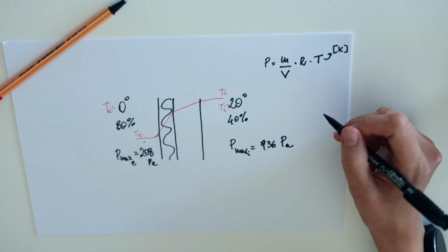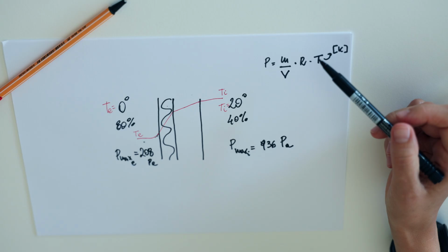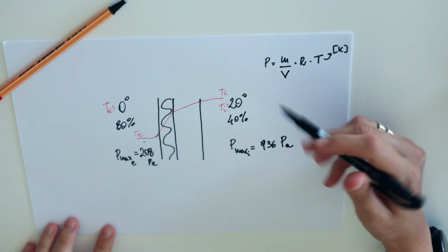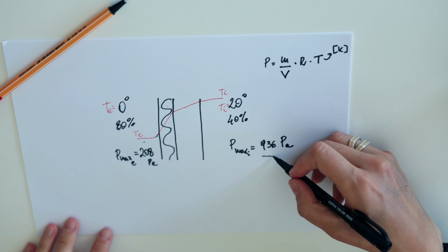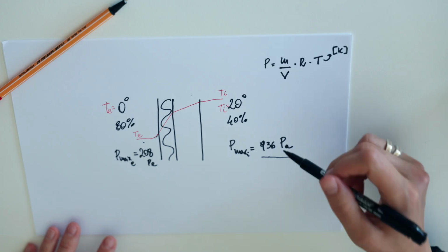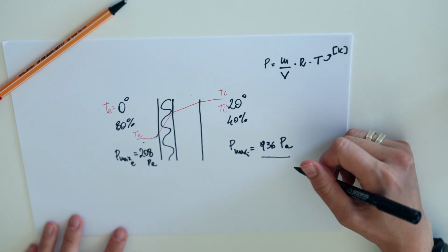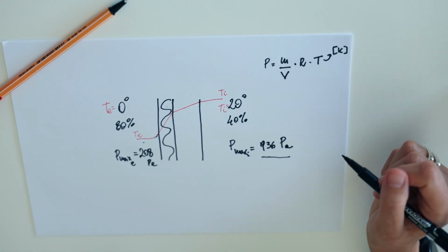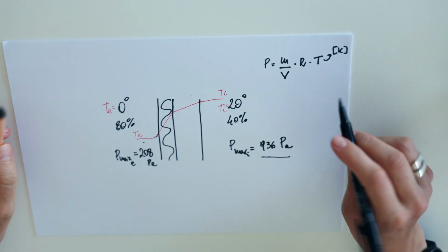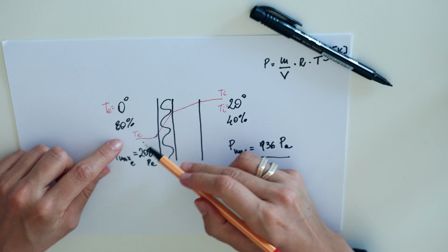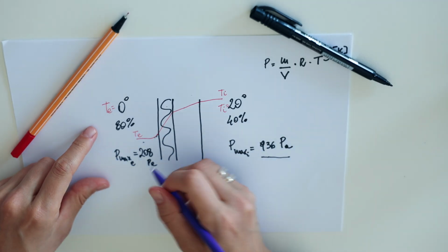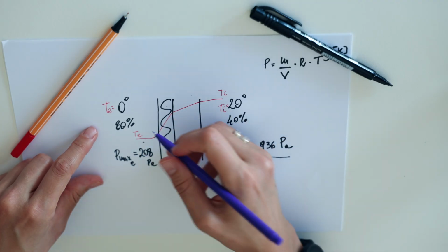Of course, the higher the temperature and the lower the relative humidity, the pressure becomes higher, which means the pressure of saturation is higher, which means it's more difficult to condensate. I have to reach a higher pressure. This is very important and it will now help us to understand if it condensates or not, because the same way we draw the temperature progression, I can draw the maximum pressure progression being here.